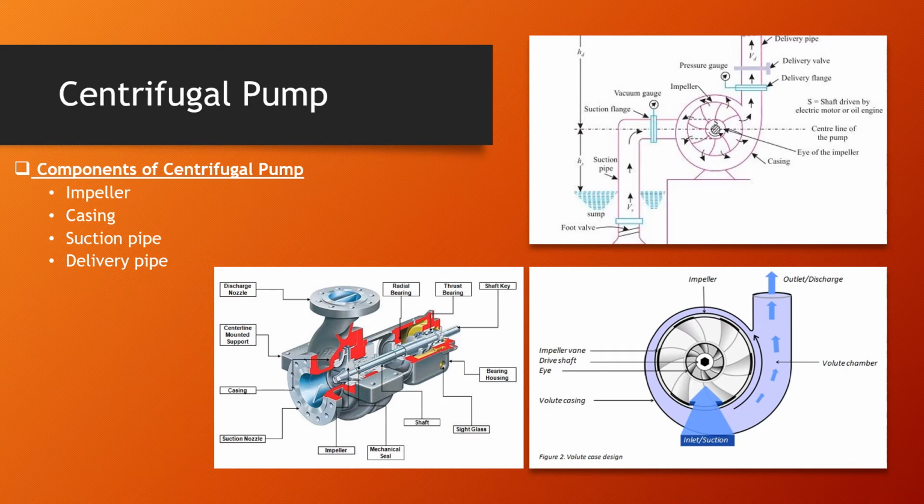So basically, a negative pressure is created, and the water is sucked from the sump to the impeller. And again, the water is imparted energy by rotational motion and centrifugal motion, and it goes out through the discharge. And that's how imparting energy to water keeps on going throughout the process.